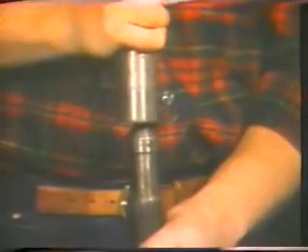In some cases, the wireline specialist may choose to drop a Go Devil before the cutter bar. The Go Devil is used to provide a base for the cutter bar to mash the wire against. The Go Devil is slotted its entire length and is designed to be pinned to the wire line. After dropping the Go Devil, a cutter bar may then be dropped to cut the wire line at the top of the Go Devil, after which the Go Devil can be retrieved.